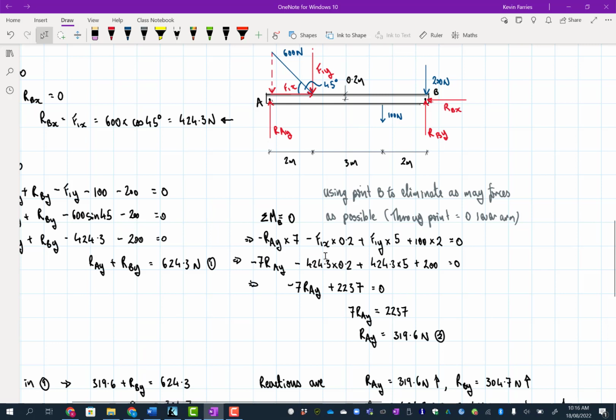So it's negative. Now you might have noticed in the fast forwarded calcs, I actually got that wrong to start with. So always I'm checking back to make sure it makes sense. If I've drawn these arrows on in the right direction, I should be getting all positives for the magnitudes. So if you think of these as being the magnitude of that vector, you've drawn the vector in the right direction and you've used that direction to get your moment. Then you should never get a negative result for your magnitude. The only time you get a negative result for your magnitude is if you'd drawn this in the wrong direction. You'd use that wrong direction for your moment, and then it would come out negative and you'd realize, oh, I need to change the direction of that to the other direction.